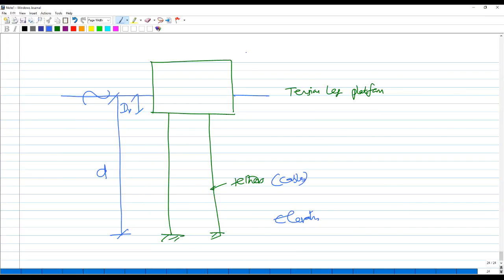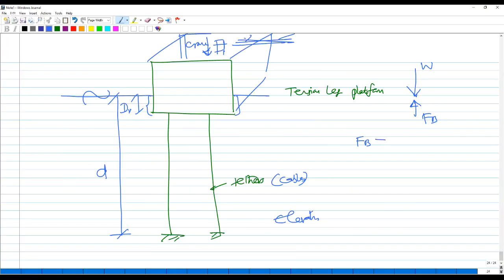The system contains a superstructure. The superstructure will have different sets of operations like crane loads, then equipment, derricks, all of which impose a live load. So the system will have a weight which is acting downward. Now when the system is immersed, there is a submerged volume of material and members which will also offer a buoyancy force upward. The system is designed in such a manner that the buoyancy will exceed the weight by a large amount. When this happens, the system will start floating.